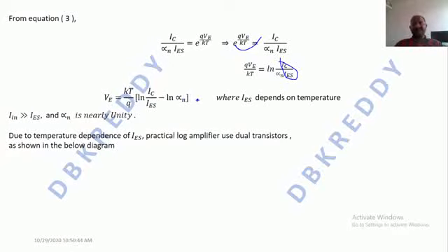Now, log natural alpha n. But we know that alpha n is nothing but the current ratio. It is the current gain, actually the forward current ratio. We usually get that as 95%, meaning 0.95, 0.99 or 0.95, like that. We have the value for alpha n, which is the forward current gain in the common base configuration. In the common base configuration, alpha n is nothing but the current gain, which is approximately equal to 1. So when it is approximately equal to 1, then log natural of this one becomes 0.